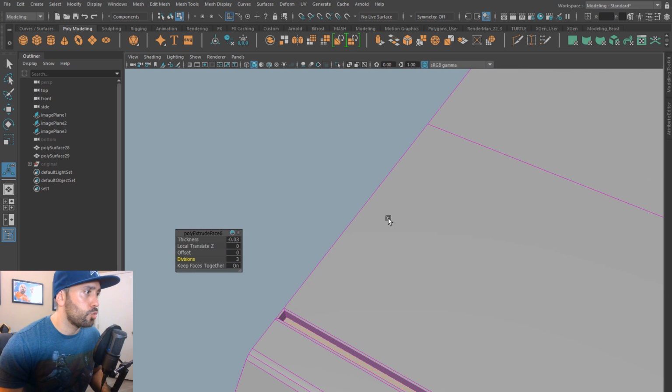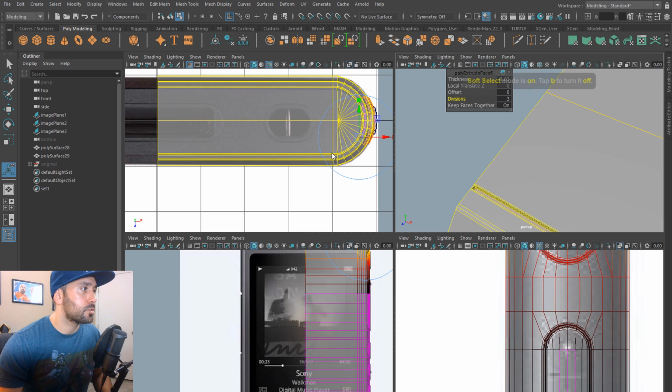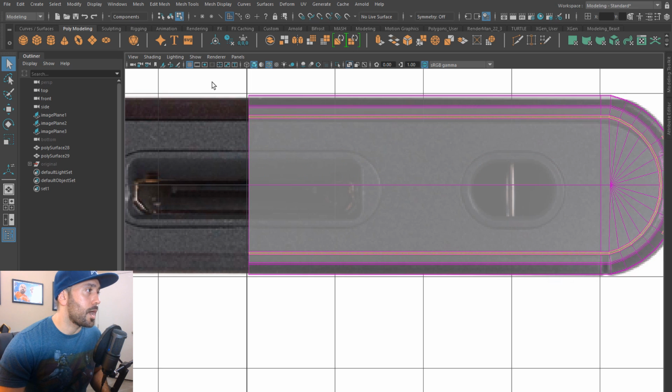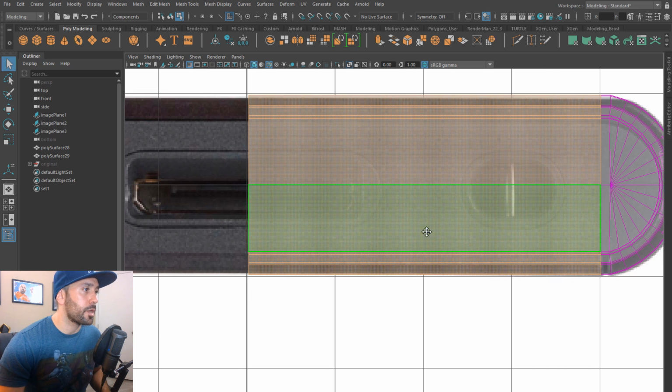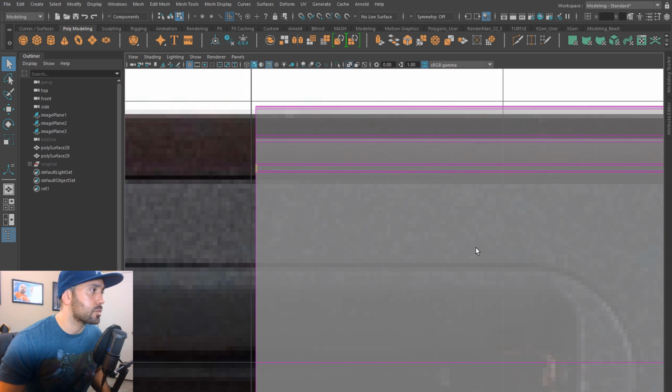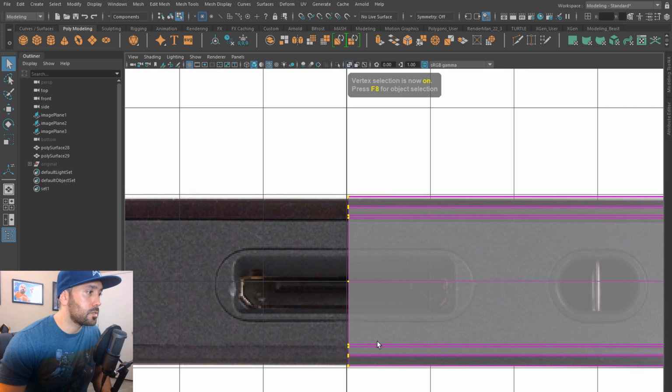Anytime that you extrude near a symmetry line, you have to get rid of these polygons here. So for that, we'll jump back to the top. I'll go ahead and drag marquee here and then just deselect everything. And you see that we have the smaller faces selected there. And now we can just take this and we'll just scale flat.